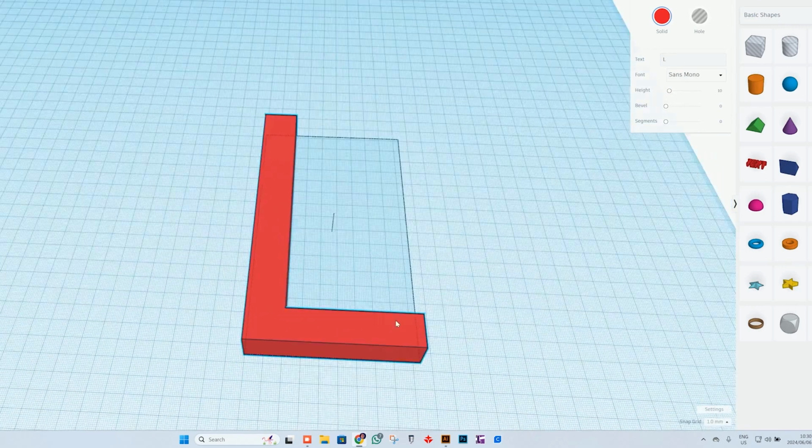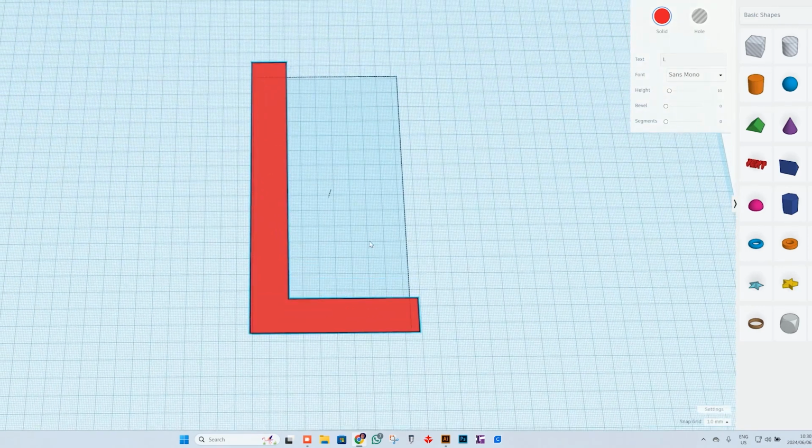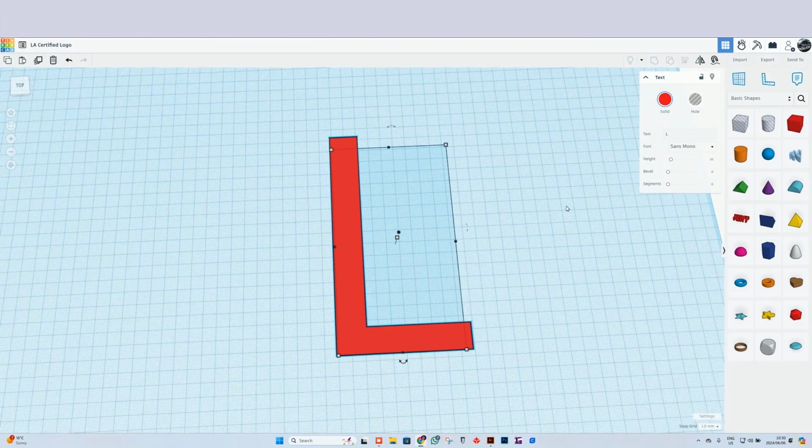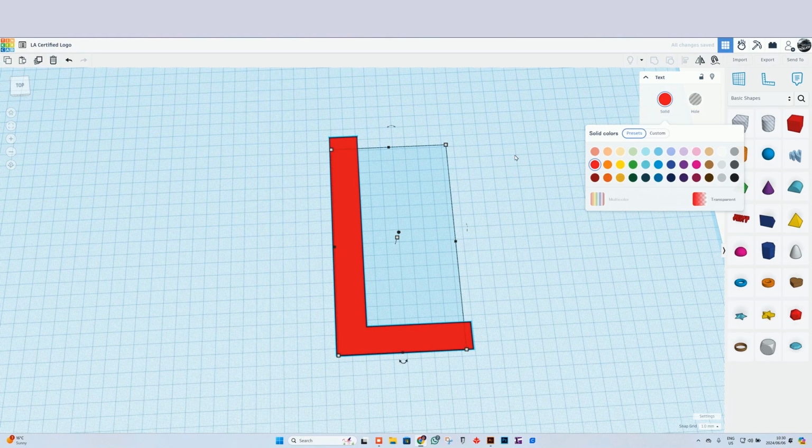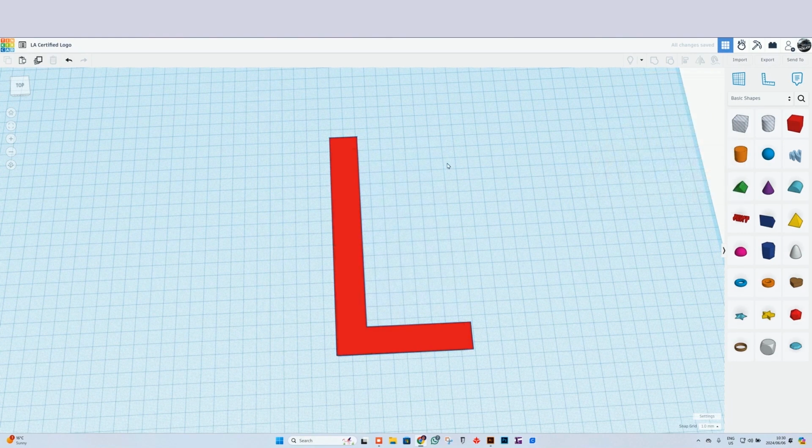Next thing we can do is shift over to the top side so we can see from the top. Now we need to create a little hole that we can punch out of our base layer, and then we can start creating our channel. So we'll click on the basic hole here. We make sure that our segments and sides are max, otherwise you get a jagged circle.